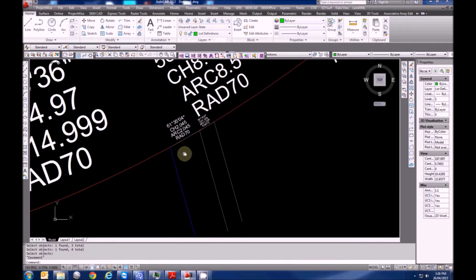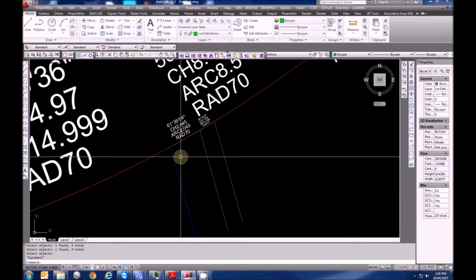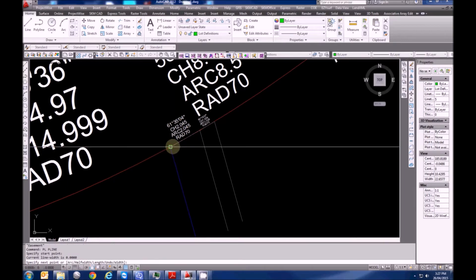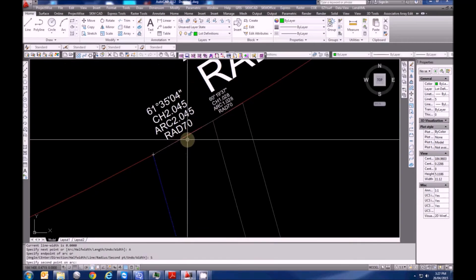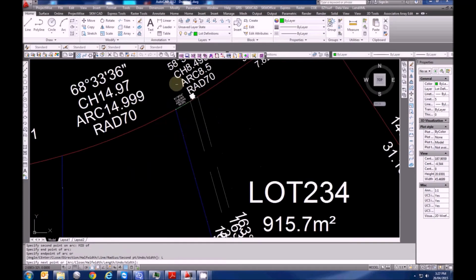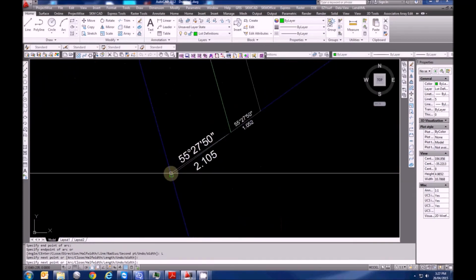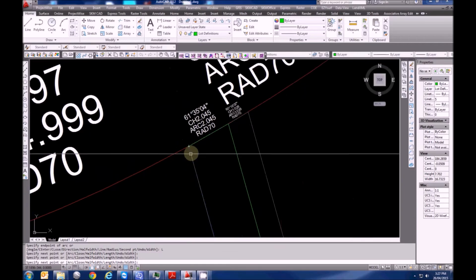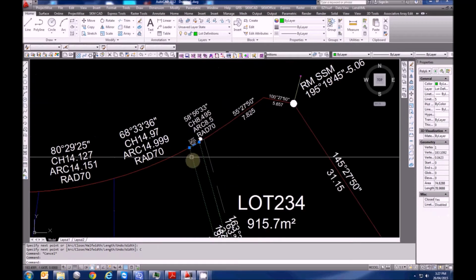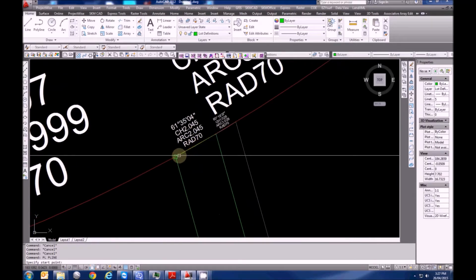So I'm going to select lot definitions, which is where the areas for the lots go, and we're going to draw our first easement, which is 2 wide. Here we go, using the polyline tool, a standard AutoCAD tool. We've done arc, second, the midpoint of that line we created, and then we're going to switch back to line mode. And up, I'll just type in close. Okay, so there's our lot, and then I'll just do our other one while we're on the go.